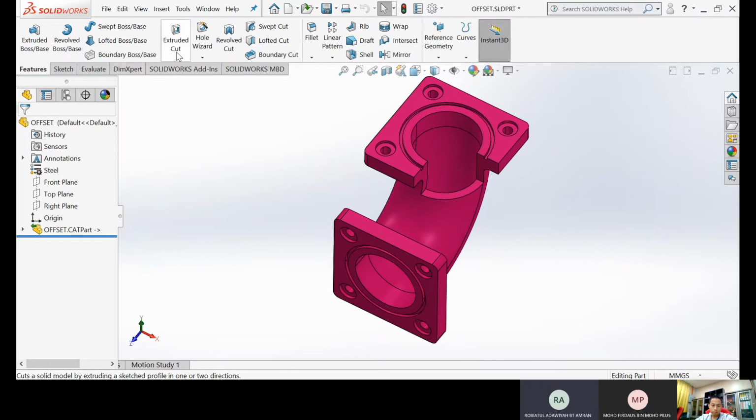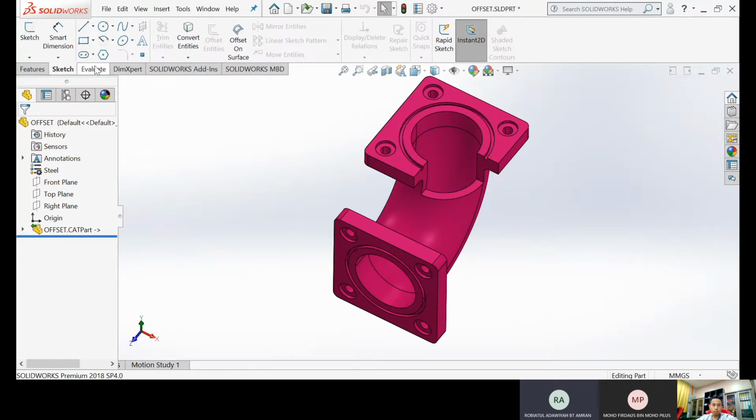The curve is used to extrapolate curvature information from the STL. The surface is used to create a surface. There are two main options that can be used. First, automatic creation, which automatically goes through and creates patches of the surface based on the STL edit that has been done. Second, guided creation, which is to create a closed fit surface and produce a better result in the end of the process. Eighth, deviation analysis is used to take a closer look at the resulting information. Next, part 2, the STL edit.